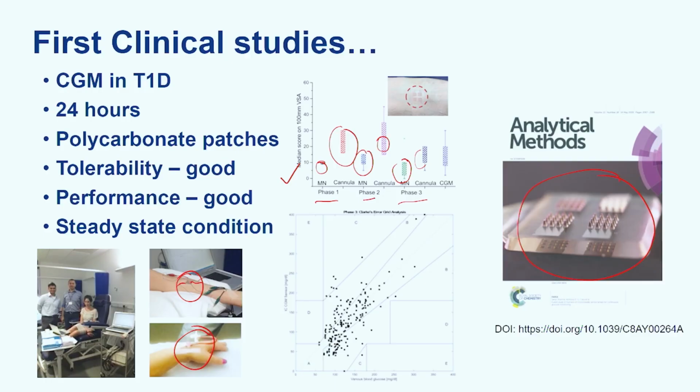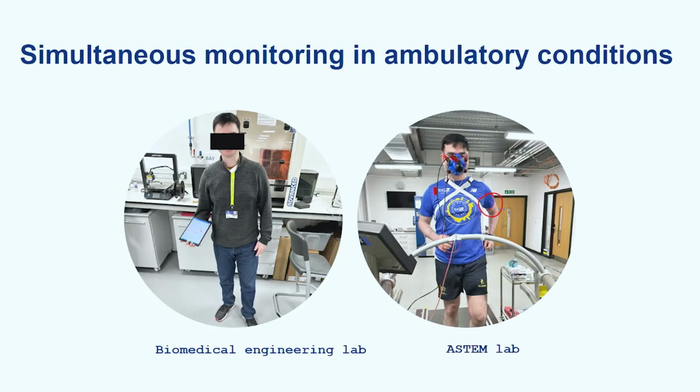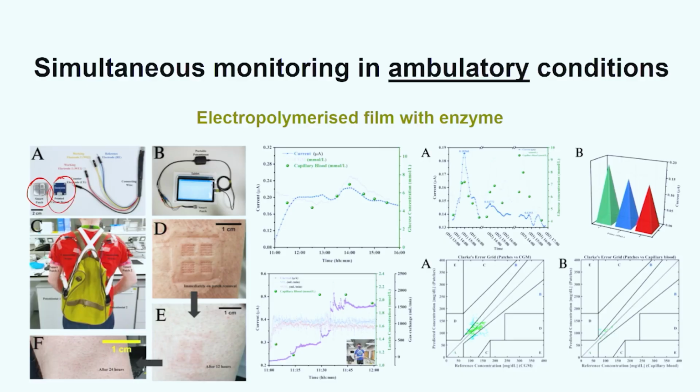I hated that, because I would be sitting on the chair, and suddenly I would wake up and see one of the connections had come off, which meant that you would start again. And that's a real pain in the backside. So the next thing you want is more stable connectors, and that's why we have these PCB connectors here, proper mini USB type connectors, so that you have stable connections. You can see this goes into that side, and then you have your wires nicely color coded, and even that one goes in and it's nicely secured. You have to make sure your connections are really well secured here.